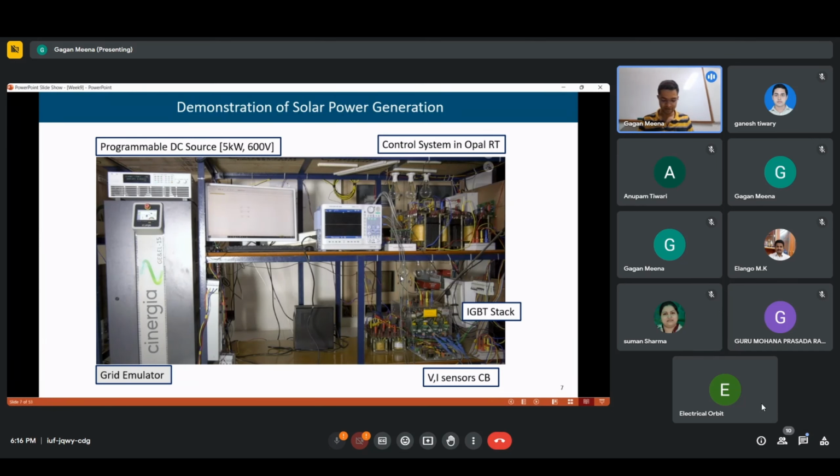So before actually installing any big renewable plant or even installing any kind of relay or PMUs, we first of all have to do a study. So we do simulations. We use different types of simulators. PSCAD is one of them. RTDS is another one. So we will make the actual physical system inside that simulator, and that actual system will be mimicked by that simulator.